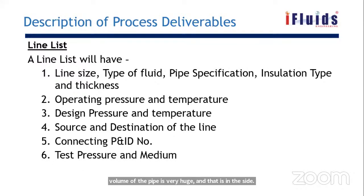That means this is applicable only for low pressure service, like flare lines and all, where the line size is like 36 inches. Very huge, and we cannot use water as a medium for testing. So in that case they will use air, with a very low pressure, like 0.1 bar gauge. And if they use water, they will use 1.5 times the design pressure for testing.